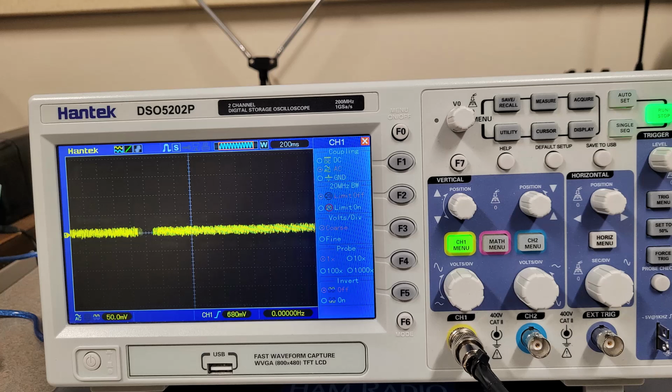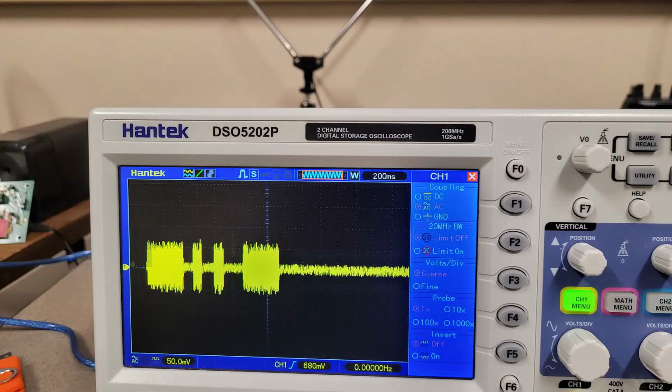The next question is, which of the following is an advantage of an oscilloscope versus a digital multimeter? Well, the oscilloscope is able to measure complex waveforms. That's AC waveforms, where voltage is changing over time. The next question asks, which of the following is the best instrument to use for checking the keying waveform of a CW transmitter? Again, if you're checking waveforms, you're checking complex AC signals, an oscilloscope is the right tool to use. Here's an example of using an oscilloscope to measure waveforms.